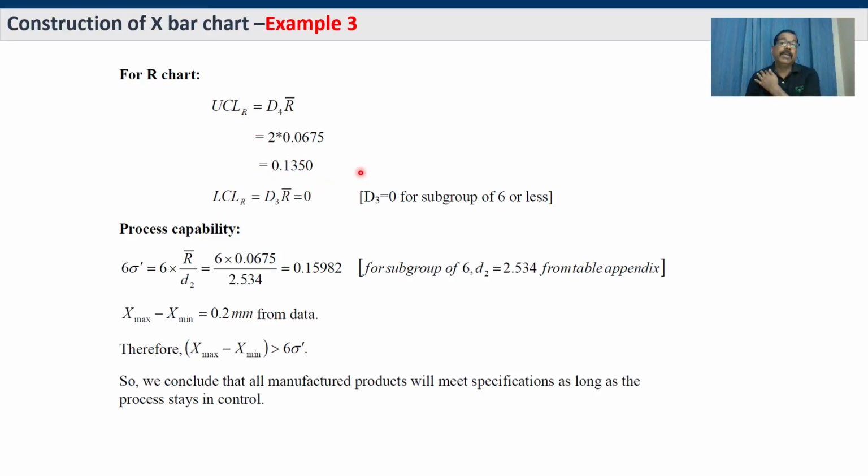That is one part. But they asked for process capability. They checked this in this particular problem, something different. So what is that? How to calculate it? In order to find the process capability, you need to first calculate six times the population standard deviation. It's not the standard deviation alone; six times the population deviation means, from the center line, 3 sigma above and 3 sigma below.